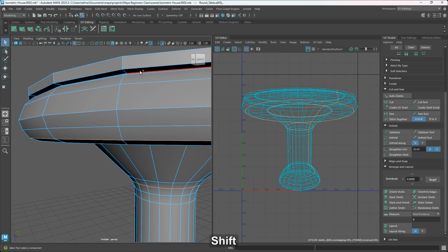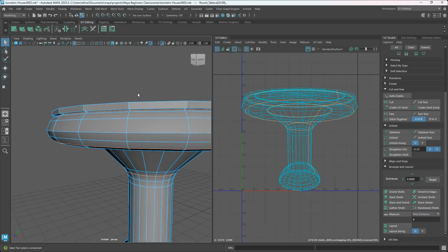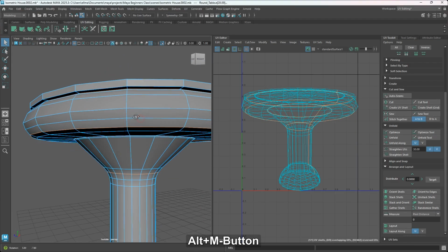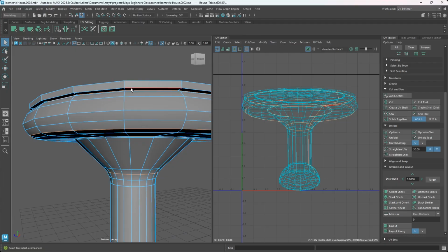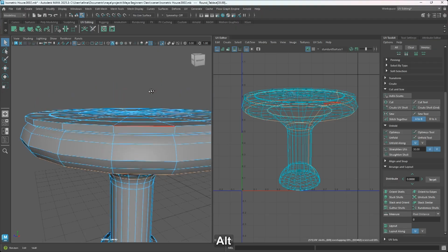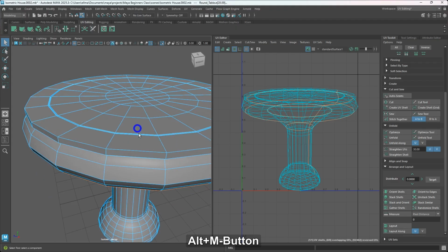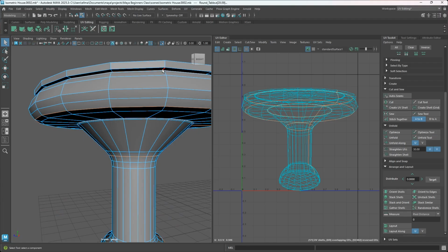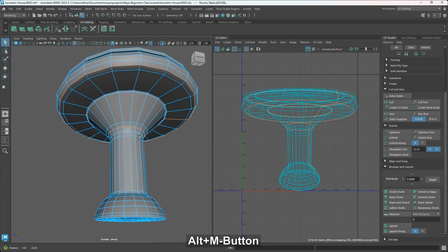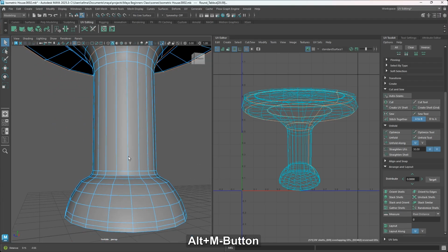Oh, okay, so now I'm going to hold down shift, double click to select that loop round, because that is where we have a cut. And here we're going to add a cut, and later on we're going to stitch it back. But I will just leave this the way it is so that we can come back and see what kind of issue we are going to have there.